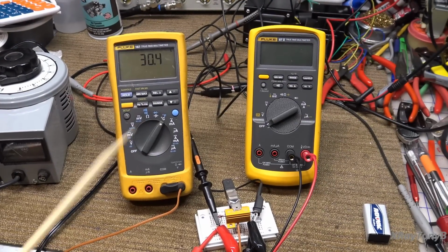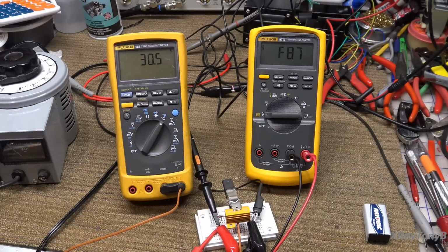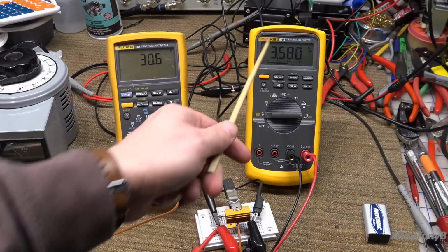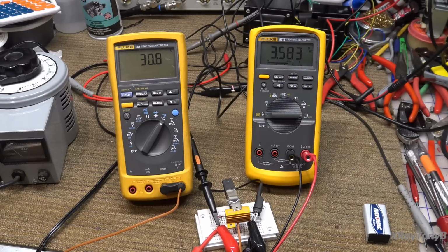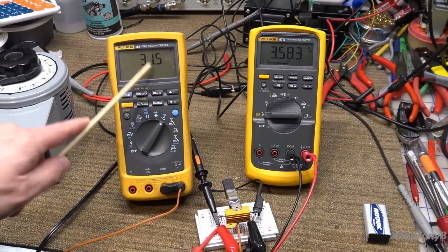Now looking back down at this, I have the meter turned off. Let me turn it on. And remember, this meter is reading different. It's not reading 5 volts, it's reading 3.58 volts. And this is that RMS again. If you looked back at that last clip that we did at the peak to peak when we were looking at the scope, if you notice, it was saying about 3.57 or 3.58 volts RMS. So I put the 5 volts on there, 5 volts peak. Let's see what happens to our temperature here.